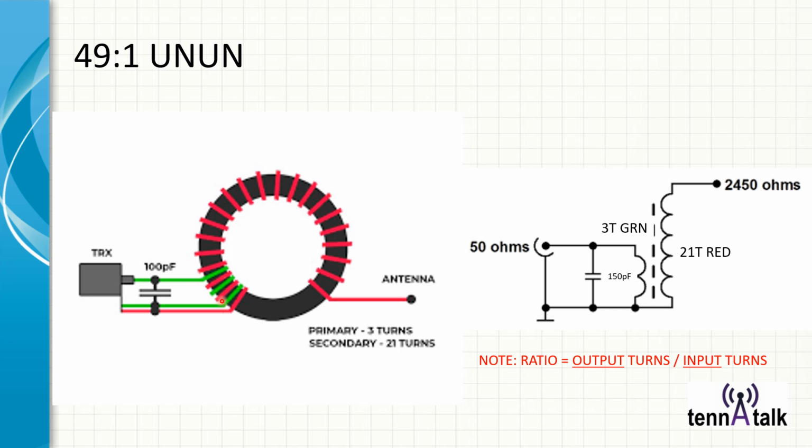It can be wound either together bifilar, the primary with the secondary, the red secondary, or sometimes people will actually twist these together on the primary side and then continue winding it around. It really doesn't make much of a difference. It's just another way to give you that tap for the center pin of your input.